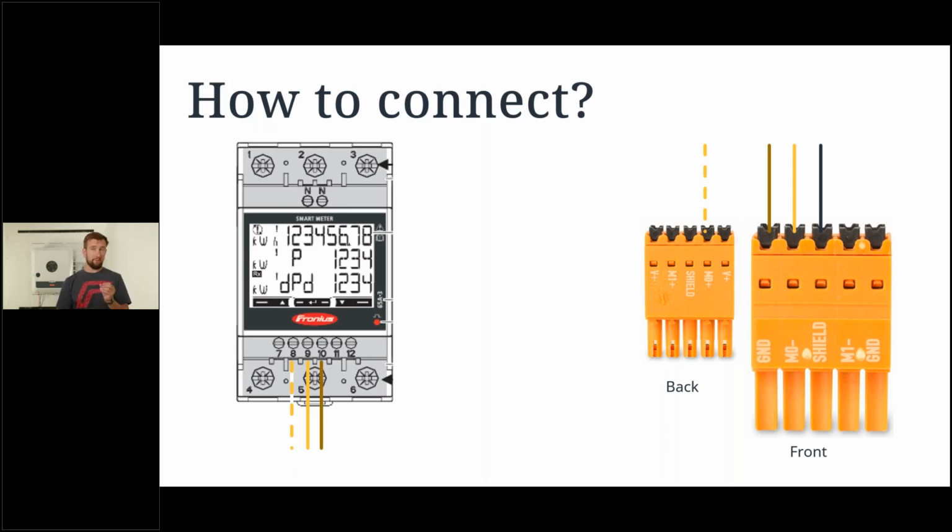If we're connecting several wires together, then we would twist them together and then insert them into a ferrule and then clamp down on them. There are also many proprietary plugs where we simply push the end of the wires in, or again, use ferrules for that. Main thing is we're creating a strong positive contact between those wires and the contact point.